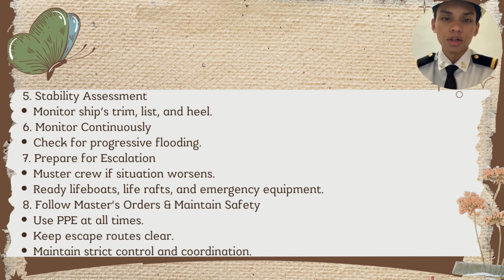Now for the 5th till 8th step. So the 5th step is to make sure of the stability by conducting a stability assessment. This is done by monitoring the ship's trim, list and heel. Next is to monitor it continuously. This is to check for any more progressive flooding.